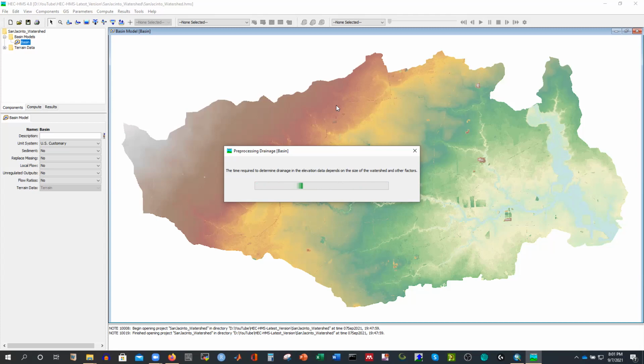And for transform method, because we will have precipitation, how will this precipitation be transferred to stream flow? We need to fix a mechanism, right? So from a depth of rainfall to the flow rate, we'll use the transform method as Clark unit hydrograph method, and we'll estimate the time of concentration and storage coefficient. But for the sake of running this model pretty quickly, we'll assume the default values, and we'll also select the groundwater bucket.